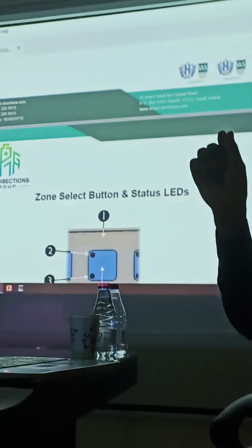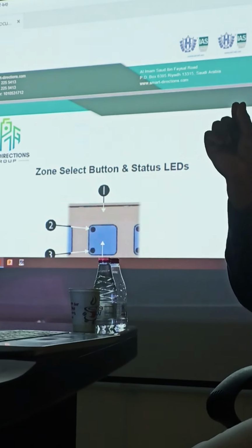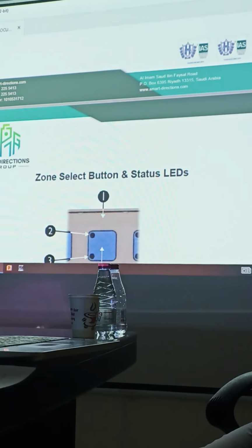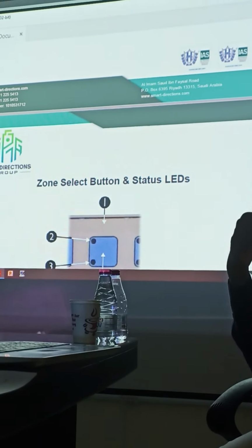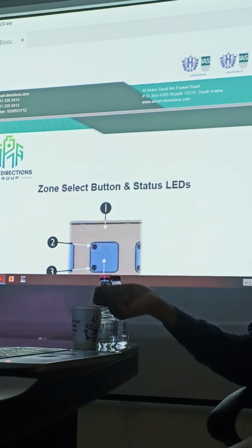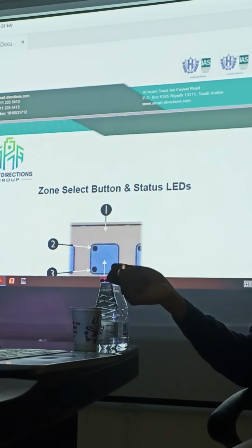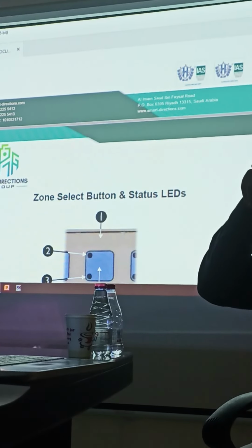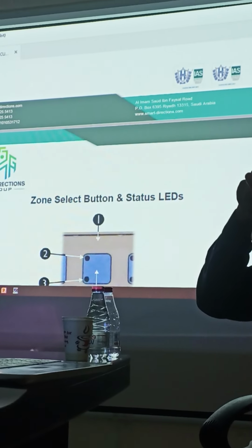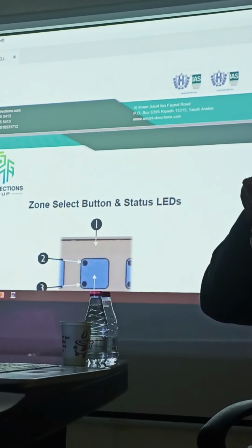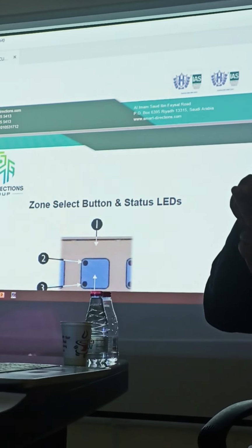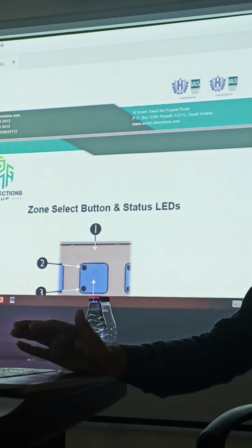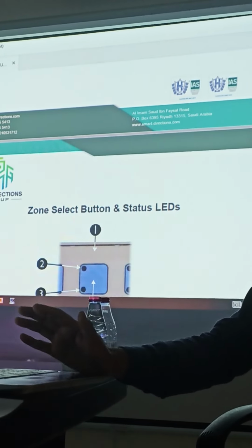There is one point where fire cables are connected. We have an interface cable connected there. So already fire integration is there. When there is a fire, we have point terminals where NO/NC contacts are there. Normally it is open. When the fire comes, it will close, and our system will work then only. It will not work without a fire.